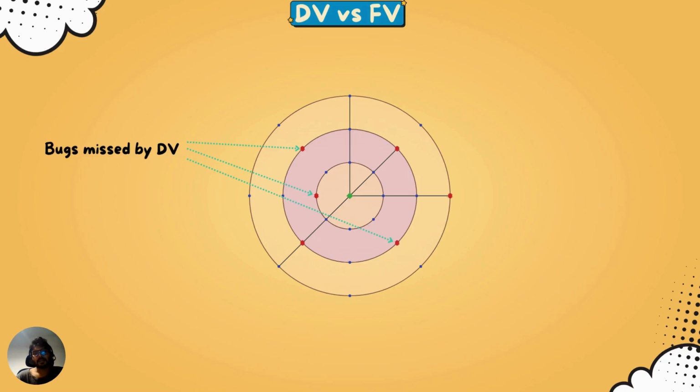As you can see, design verification, or normal simulation-based DV, can trace a few paths and it can cover, say, 3 out of the 6 red buggy states, and it can uncover those bugs. Whereas formal, given that the checks run and reach a particular cycle or particular bound, can cover all the 6 possible red dots. In short, we can guarantee the absence of bugs once it completes the run, or once the check passes a particular cycle or bound, whereas DV cannot.